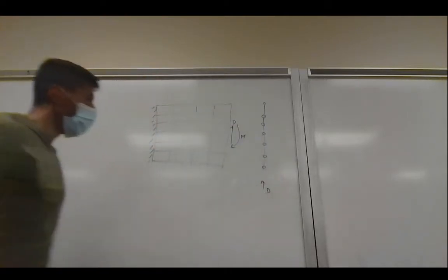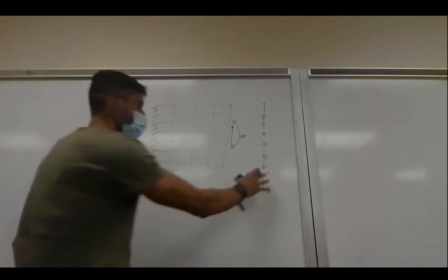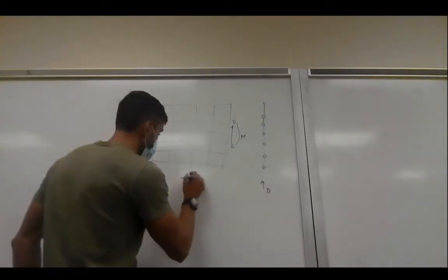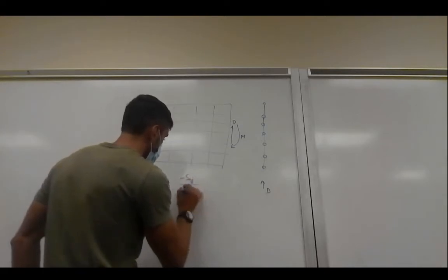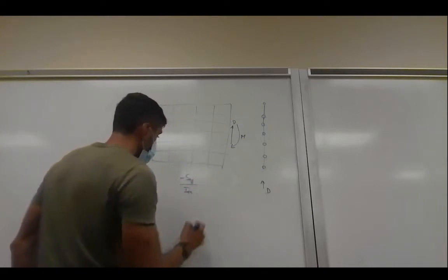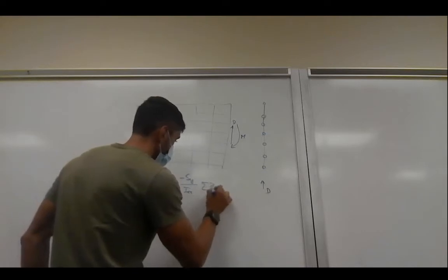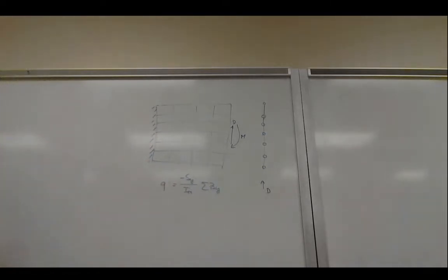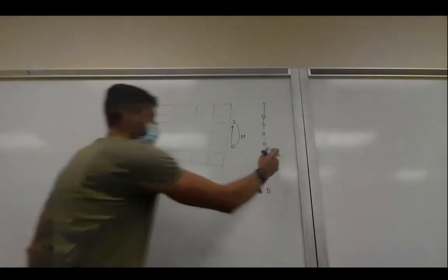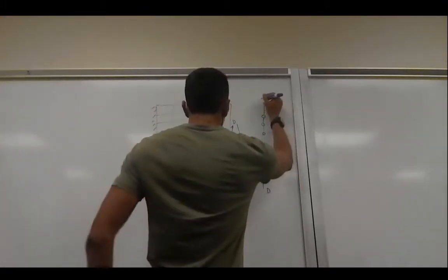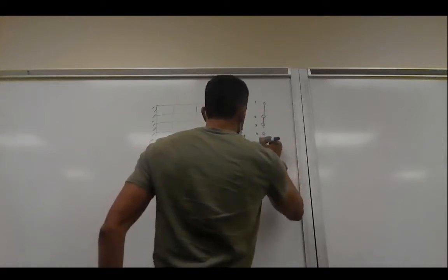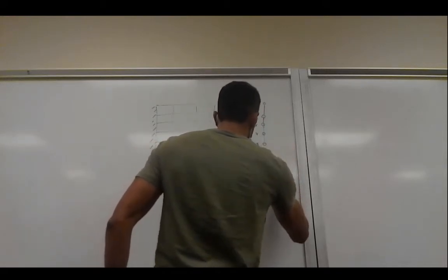And if you put the force on it, the force will be like here, right? So what you can do is, this is just an open shear flow problem. So we know from our open shear flow is Sy over Ixx. So you can just solve this and you get your, let's call this numbers, 1, 2, 3, 4, 5, 6, and 7.